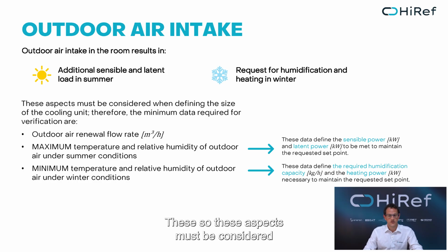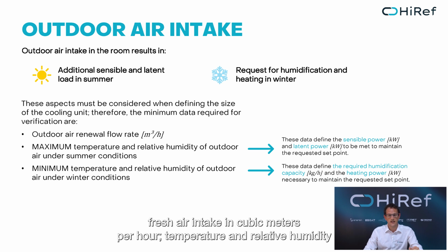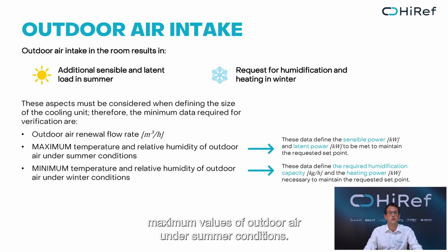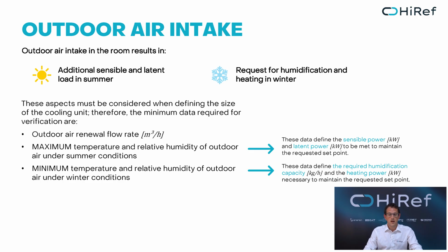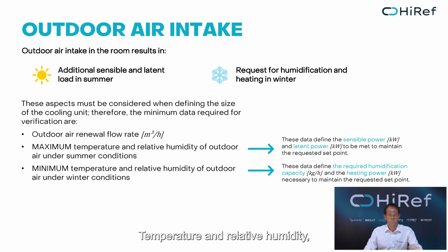These aspects must be considered when determining the size of the cooling units. Therefore, the minimum data required for verification are airflow of fresh air intake in cubic meters per hour, temperature and relative humidity, maximum values of outdoor air under summer conditions. These data define the sensible and latent power that must be provided to maintain the required set point.